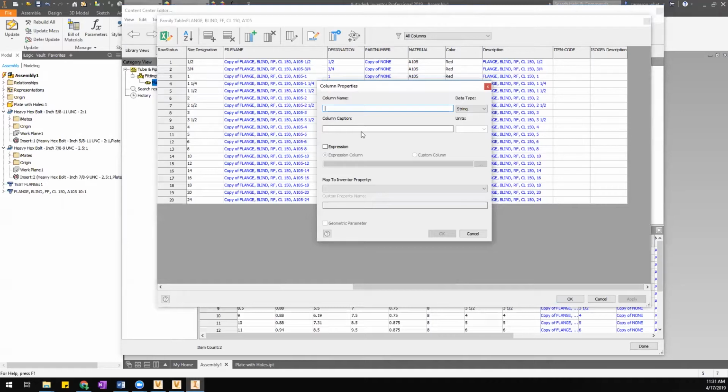What did I call it? I called it test. And it was a real. I think the type of parameter I created was a numeric parameter. Units or inches, I just left the default. This stuff has all got to match what it actually is, otherwise it won't find it and it won't match up. But there we go.